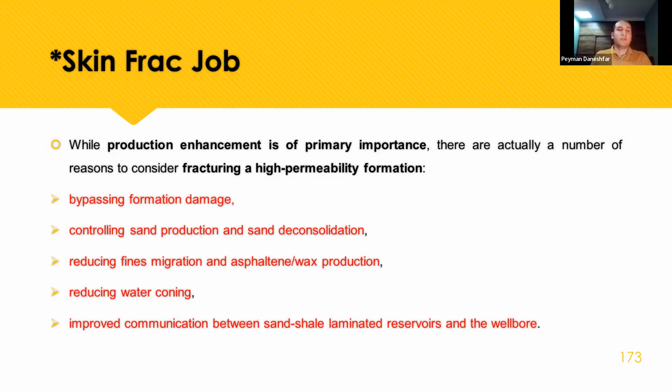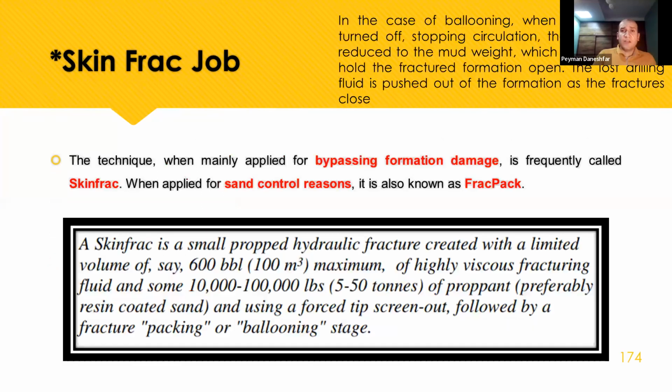This one has the objectives of bypassing formation damage, controlling sand production and sand consolidation, reducing fine migration and asphaltene and wax production, reducing water coning, improving communication between the sand-shale laminated reservoir and the wellbore, and other things.